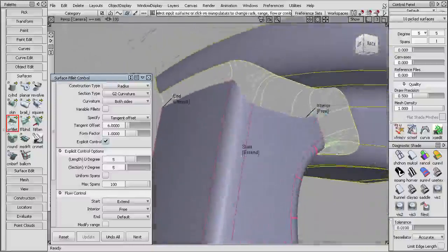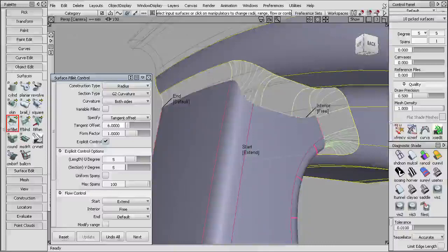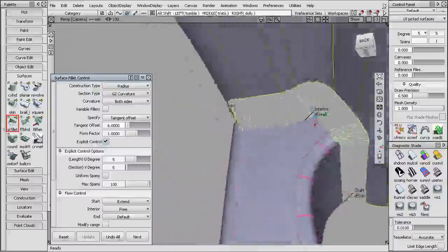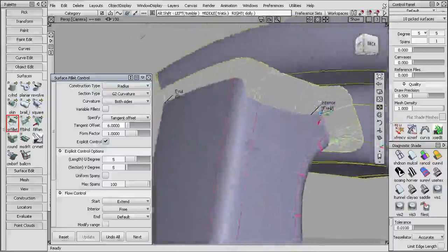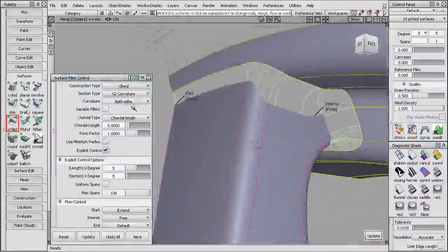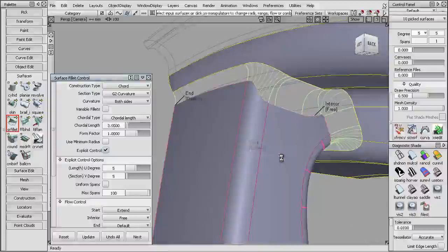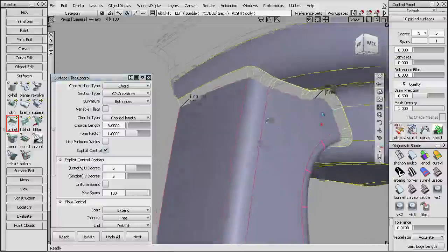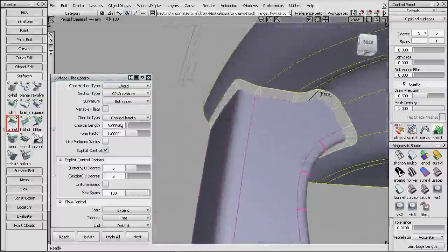And another reason to show you this large value is that it exaggerates the difference in width that a fixed radius fillet creates here. So this is where I might try the chord calculation. And this works on a fixed width rather than a fixed radius. And in this situation, it should give us a much more consistent looking blend. And I can make that a bit larger.